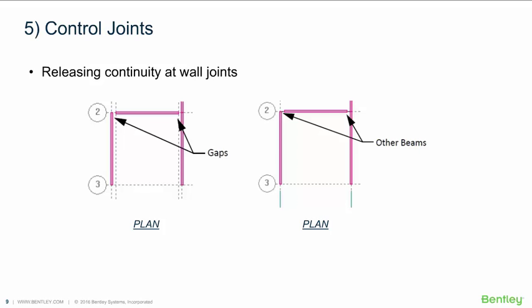You'll get that with a one-way deck, which is what we have here. And it's best to use the other material type when you're laying down the beam, because that way when you enter RAM steel, if you used a steel beam instead, RAM steel won't try to design that beam if you use a type other. Okay.